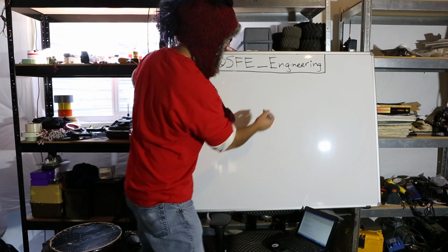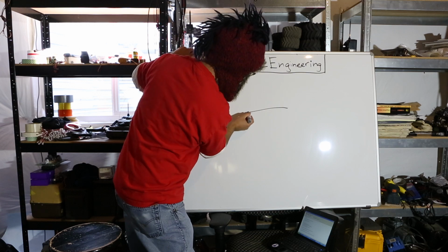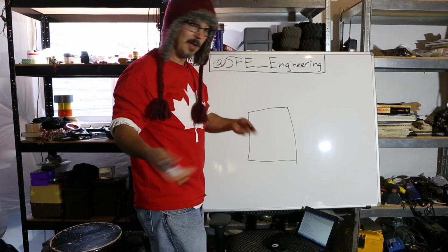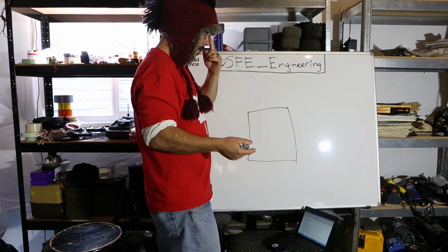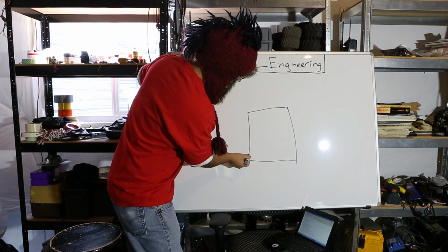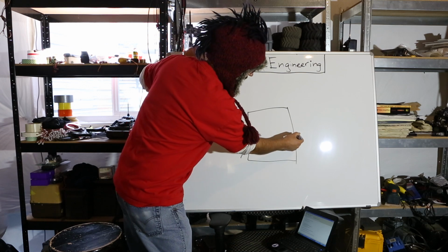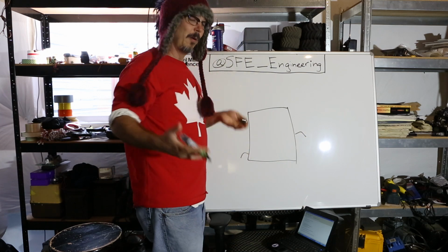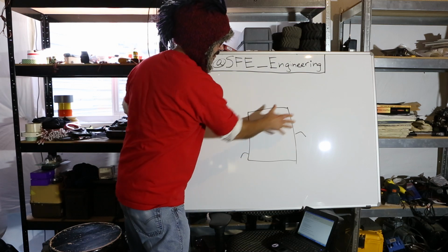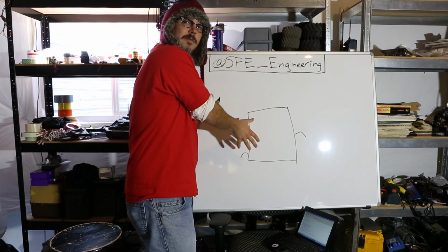What they will do oftentimes is give you analog ground pins versus a digital ground pin. And hopefully, if they've designed the chip really well, they will have those sections separated internal to the chip.